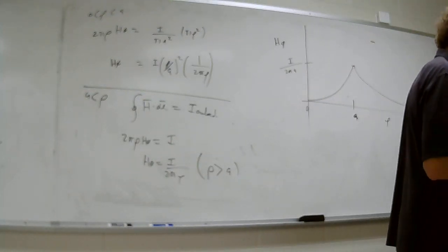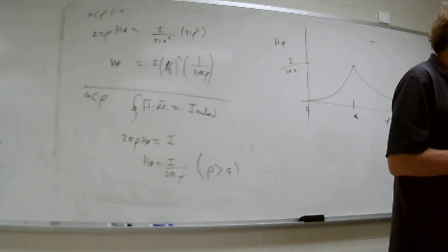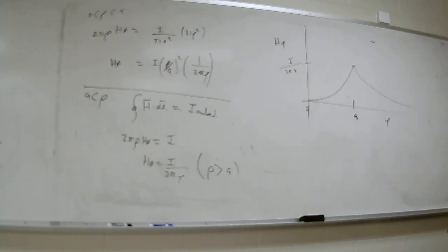Now, is that due to the skin effect, or is that a completely different thing? I'm defining what J is. Skin depth and things like this have to do with frequency variation. This is DC. So if I define what J is, in other words, you don't know how it's that way, you know it's that way, though, then you use this. Skin depth is AC. It's further down the line.